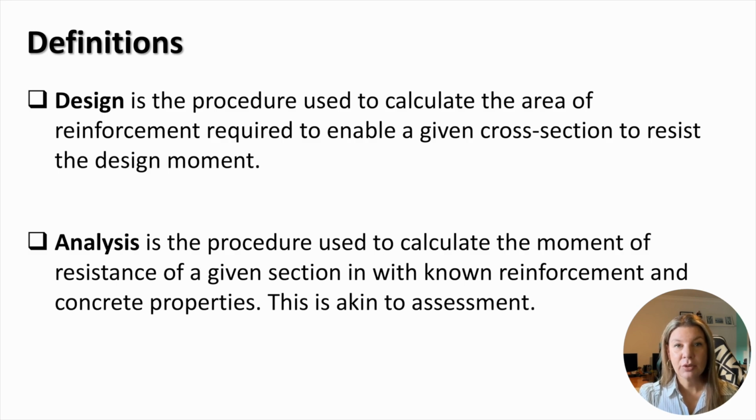Design is the process used to calculate the area of reinforcement required to enable a given cross-section to resist the design moment. Design is usually applied to new structures. Analysis, on the other hand, is the procedure used to calculate the moment of resistance of a given section with known reinforcement and concrete properties. This is akin to an assessment and usually is applied to existing structures. As you can see, design and analysis are complementary engineering processes.